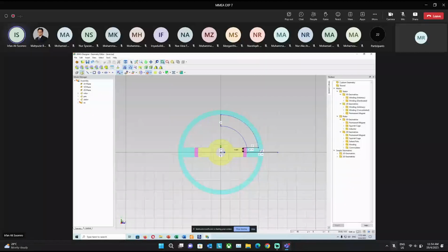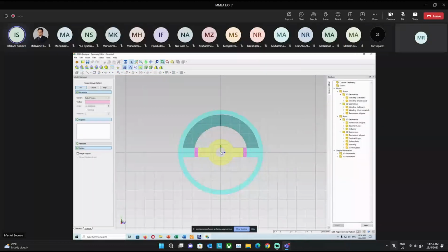Right. Now we select the created portion and create a region. The region is created, and we just copy mirror the image, and then we go to the radial portion, circular portion. Just click on both, and then the angle is 180, and it's created. No need to merge because both are windings, so we don't merge them. So our final armature coil part is also created.